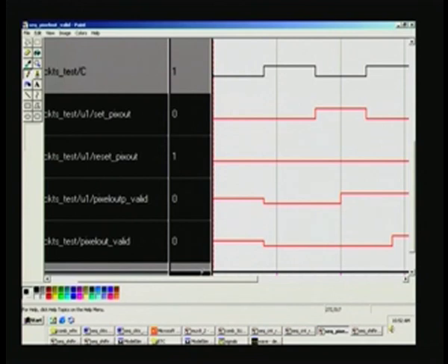The user can process further when this is asserted, and he can take the actual pixel value, and if he has storage elsewhere, he can store it at the positive edge of the clock subsequent to the rise of this. So, it therefore indicates the validity of the pixel.